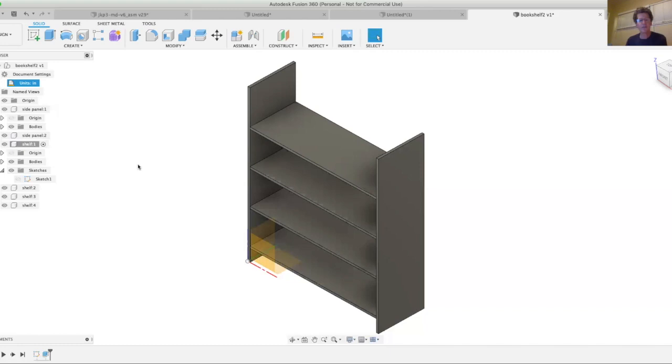And it's very useful to do a family of different things with similar features. So if you had a series of knobs, if you were defining fasteners, anything like that, you can do a whole family of them this way. But I wanted to show you the extruding to a surface rather than just specifying a length and what that means for you.